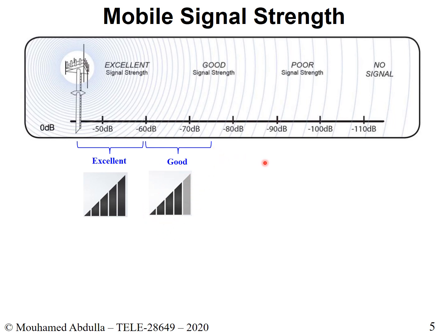And if you have anything between minus 75 dBm to minus 90 dBm, the signal is considered fair. So your receive signal on your mobile is fair. You have 3 bars on your mobile. And if you have anywhere from minus 90 dBm to minus 100 dBm, now your signal is not good, right? It's actually poor. You're still connected. You still have connectivity, but you're at 2 bars, and the quality is gradually diminishing.